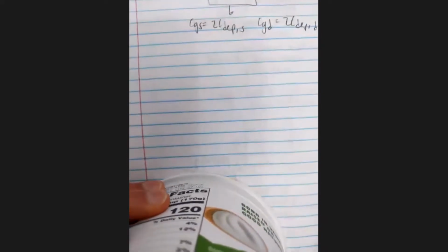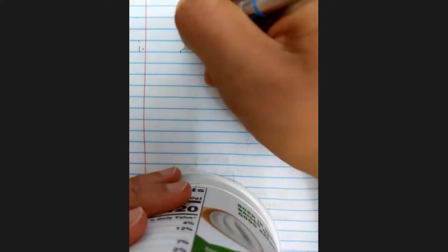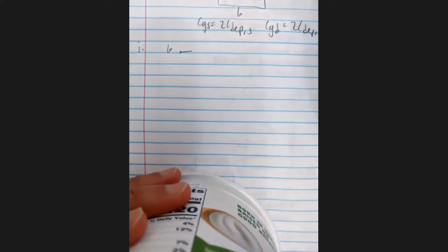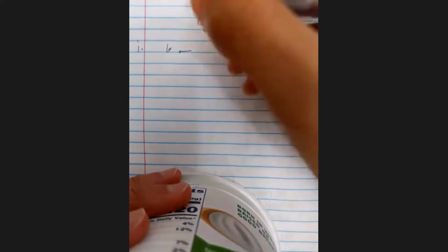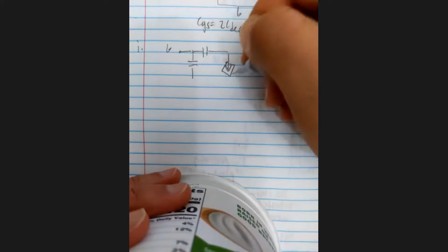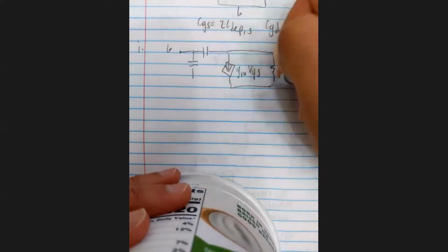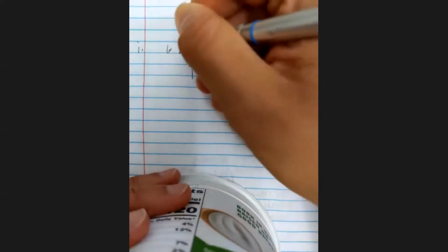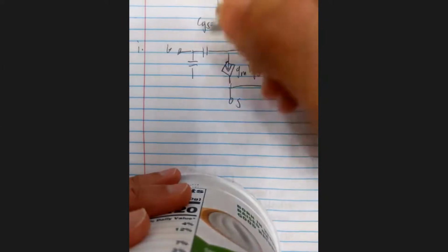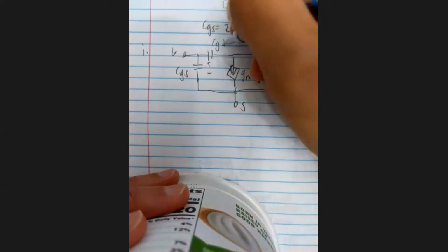So those are the capacitances in this structure. And finally, we are going to draw a small signal model. And the wording of this question implies that I don't have to do too much calculation, so I'm not going to do too much calculation. But essentially, this is the same transistor small signal model that we've seen for MOSFETs and for BJTs. So we have this gm vgs. We have an ro. This is the source. This is the gate. This is the drain. And this is CGS as we calculated it above. And this is CGD as we calculated it above.